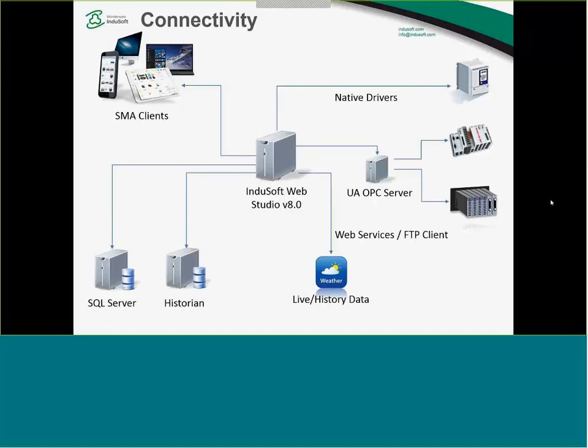And here I just put another diagram, now talking specifically about UT. What are the types of connections that you are using? We have some native drivers that talk with some devices. We rely a lot on the OPC technology, as Roberto mentioned, so UT uses a lot of OPC technology. It was really important that we supported UA, or the Unified Architecture OPC technology, because as Roberto showed on that diagram, UT uses a lot of remote OPC connections.